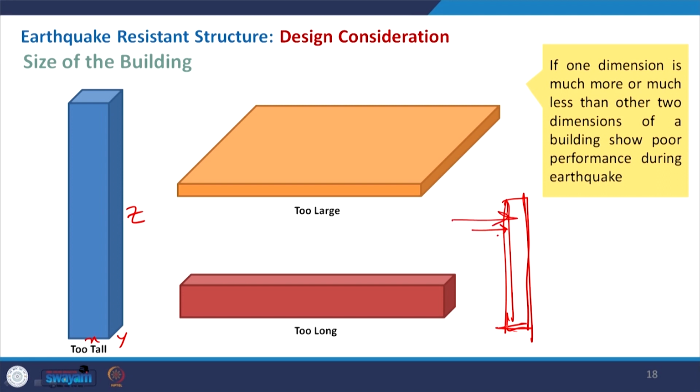But even when it is anchored, this will have much more deformation during an earthquake. Okay, so this will create some kind of structural failures. This will be very vulnerable. So, a simple frame structure may not be appropriate if this is being constructed in an earthquake prone area. Normally, an earthquake cannot be predicted accurately, but the zones are specified, so obviously we have to take that chance as a factor when we go for the structural design.